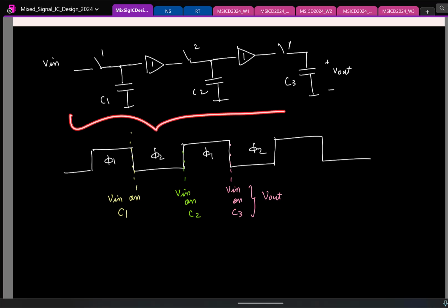So this is one way to create a delay for analog signals, and in recent times these are very popular for creating what are called beamforming systems. Beamforming, loosely speaking, is where, if you have an antenna, it transmits in all directions. Now let us say I don't want to transmit everywhere. I want to transmit only to him. So I'll make sure my beam is directed towards him.